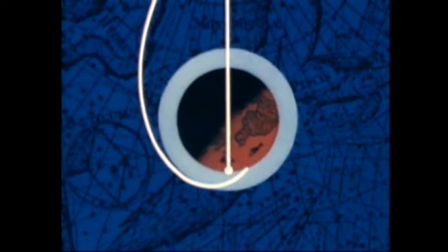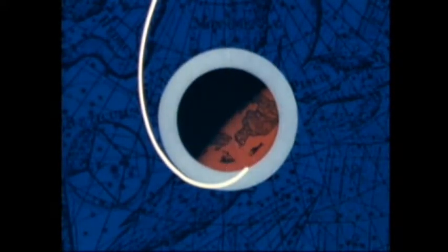The distance from the point of entry into the atmosphere to the antipode is relatively fixed. The entry range limits of the spacecraft are also fixed, so that landing occurs near the antipode. Therefore, the landing area is defined, and the target point can be selected within this area. The recovery forces are, of course, located on the surface of the Earth and rotating with it, while the trajectory is fixed.